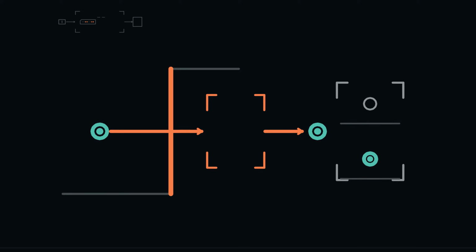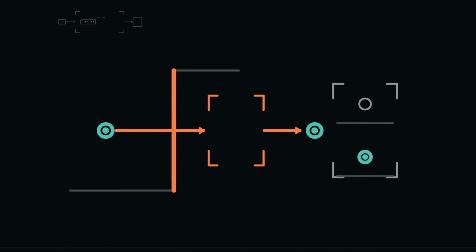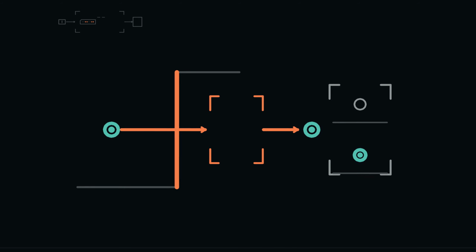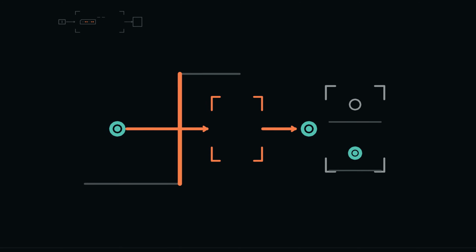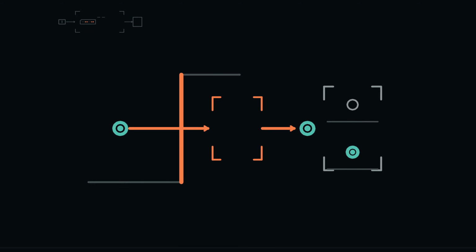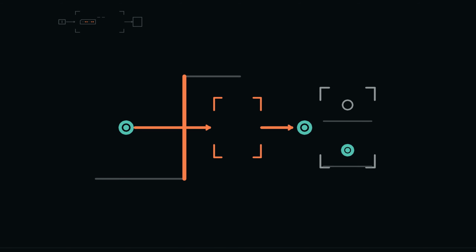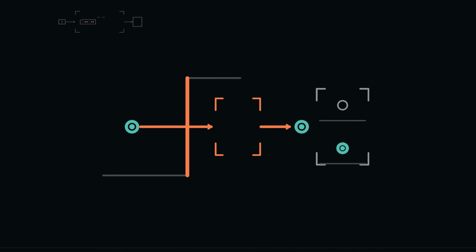Start with Q equal to 0. Well before the first rising edge, D settles at 1. The old state column remains Q0 right up to the edge. The edge arrives, the ledger copies D equals 1 into the new state column. After propagation delay, Q becomes 1. Nothing traveled from a clock lane into the data cell. The clock event authorized capture, while the data input supplied the value that was captured.